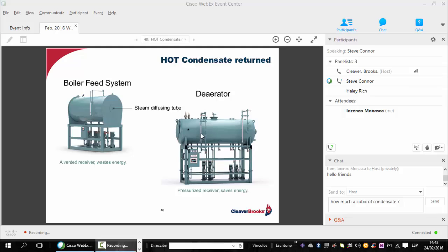So these waste energy, for sure. And to say nothing about the higher chemical and blowdown costs due to higher percentages of sulfite that has to be added to this boiler water to combat the oxygen corrosion issue.